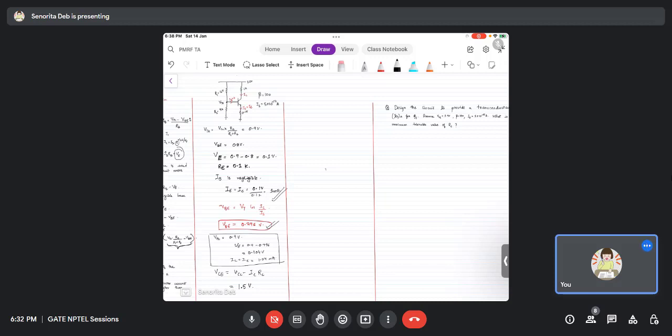So we saw that if we introduce an extra resistance in the emitter, the base current IB can be made negligible, because the extra dissipation because of the variations of the resistor value will come across as a voltage across RE, and therefore my base current will remain negligible. So this is so far considered the best, most stable circuit. The stability factor is highest in this.